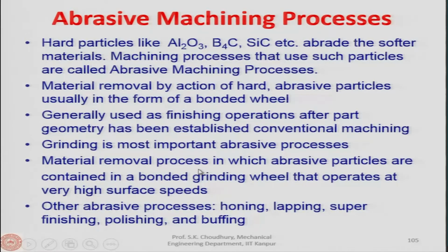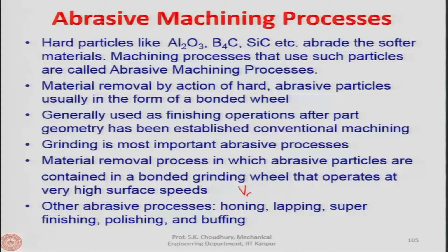It is a material removal process in which abrasive particles are contained in a bonded grinding wheel that operates at very high surface speeds. When we say the grinding process operates at a very high speed, it is really very high, like 10 to 80 meters per second.